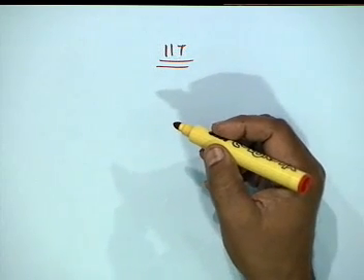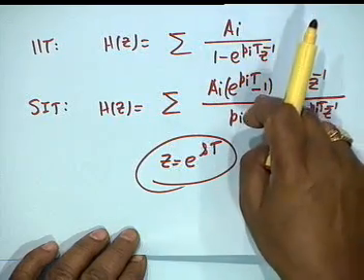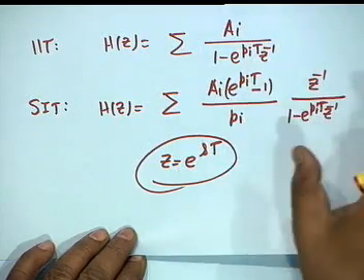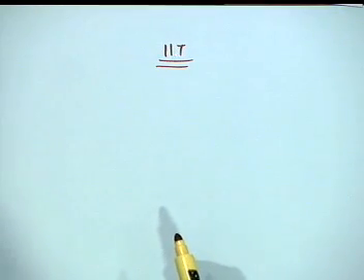Excuse me, sir. What is the implication of 0 at infinity? Well, it makes the transfer function different. If in each term you add a z inverse in the numerator, the transfer function is different. Okay? The implication in terms of frequency response is difficult to say because there is a summation, and these constants are important in the summation. Depending on these constants, you can get different transfer functions. So it's difficult to say what is the implication on the frequency response.